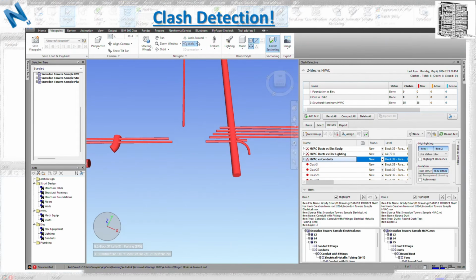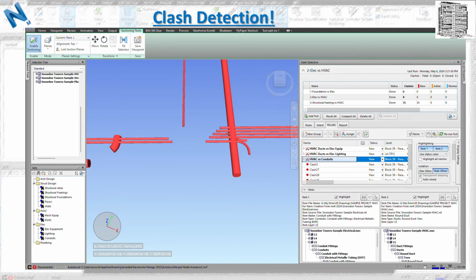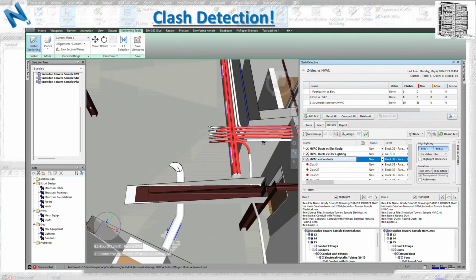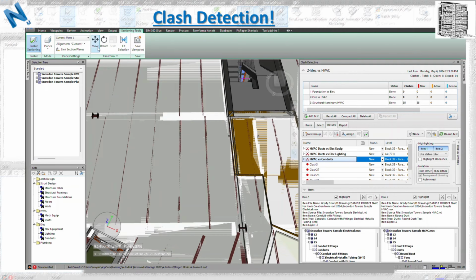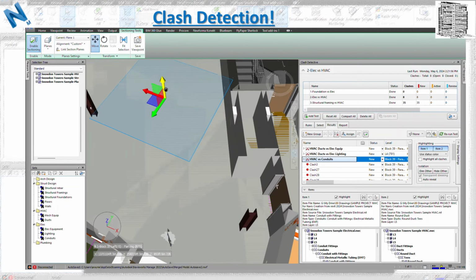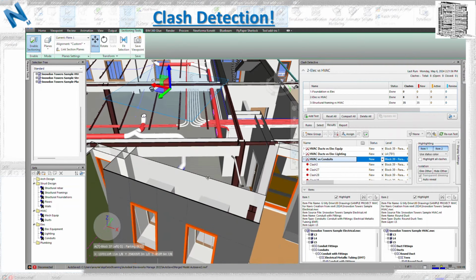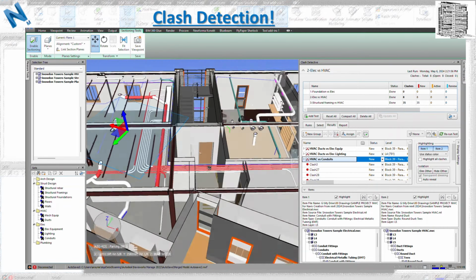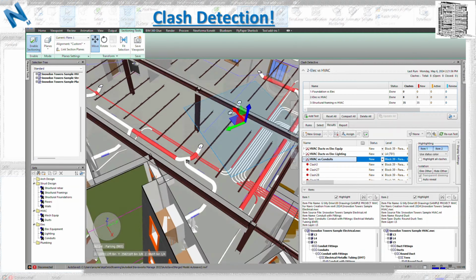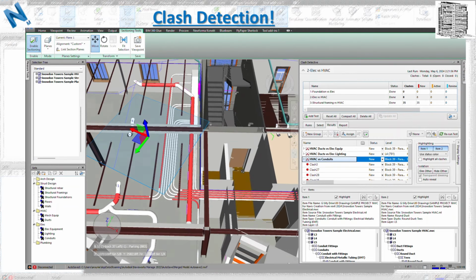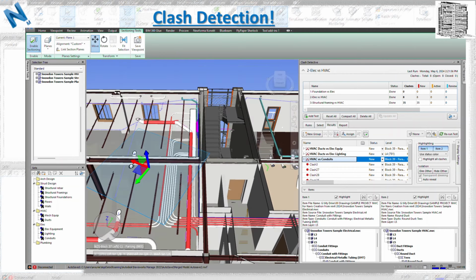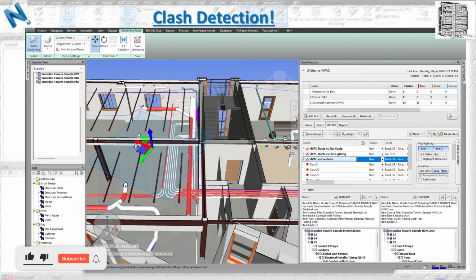But if you want to get to it, you can use your selection box. You can get to that area and align it to that surface. You have the move tool. You can push it up and down to get to the clashes that are behind the ceiling or behind the slab or below it. You want to get to those items and take a look at them, see what the areas are. So this is just HVAC versus conduit that we are taking a look at.